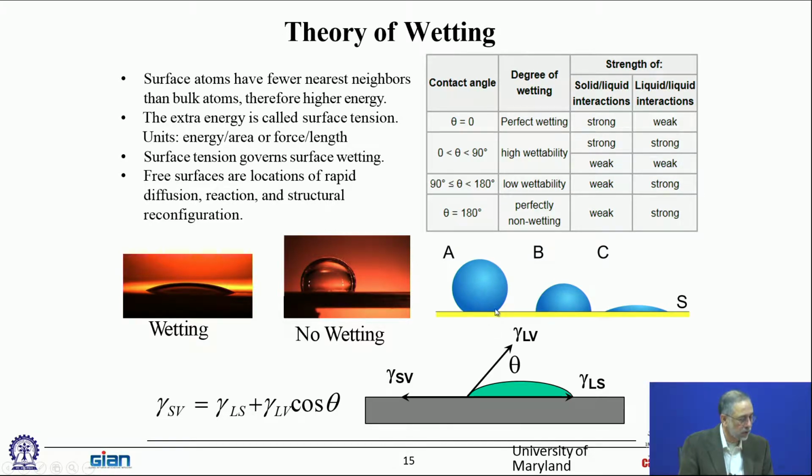And the surface energies have to match between the solder and the surface you're soldering on. Otherwise, this is clearly a non-wetted solder ball, and so you put a bead of solder on that plating. This did not wet. This one kind of partially wetted. This one wetted very well. Okay, so when there's good wetting, it'll spread out. So this angle, therefore, this contact angle, is often used as a metric of how good your wetting is.